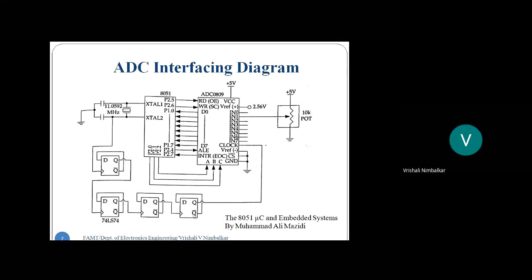Correct? Now, what is the frequency that is selected? See, students, a single flip-flop divides the clock by 2. So if I say this is 12 megahertz, the first flip-flop will produce 6 megahertz because a flip-flop acts as a divide by 2 frequency divider. So 12 megahertz, output of first is 6. Output of 6 megahertz as a clock to the second is 3 megahertz.